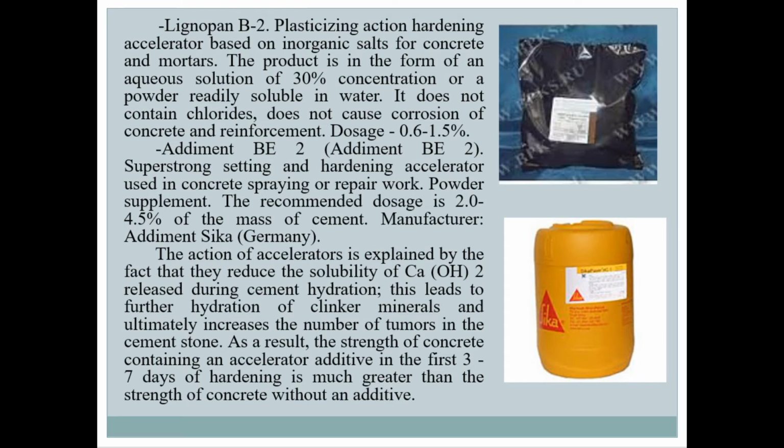hydroxide Ca(OH)2 released during cement hydration. This leads to further hydration of clinker minerals and ultimately increases the number of new formations in the cement stone. As a result, the strength of concrete containing an accelerator additive in the first 3 to 7 days of hardening is much greater than the strength of concrete without an additive.